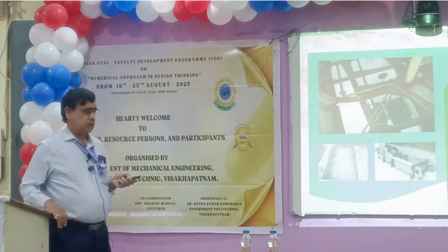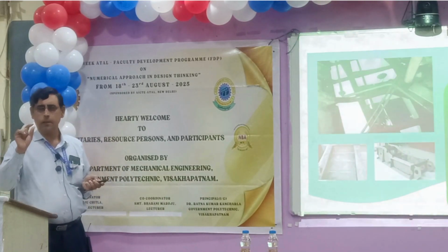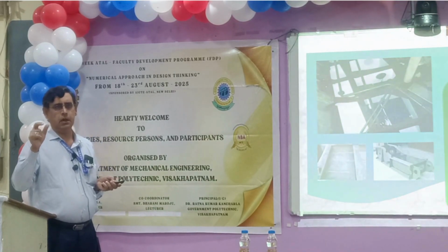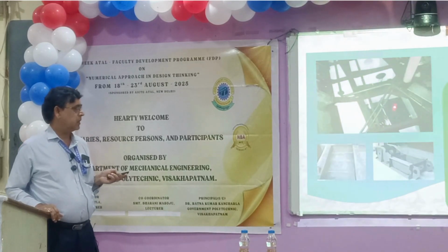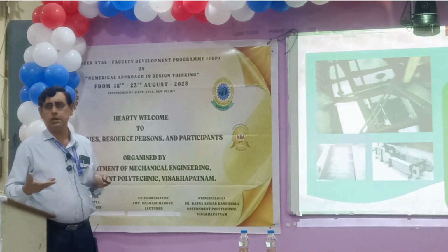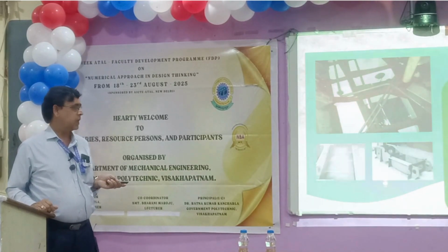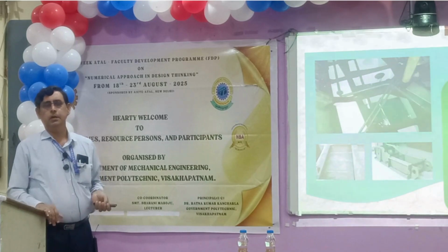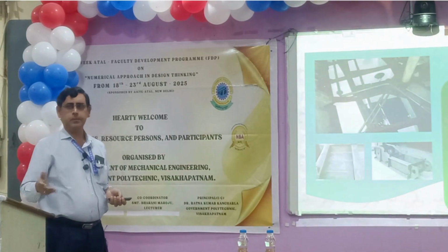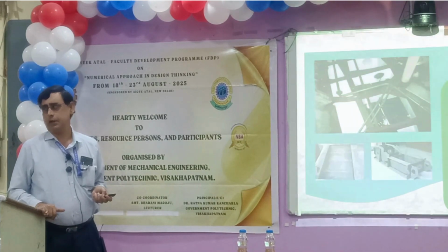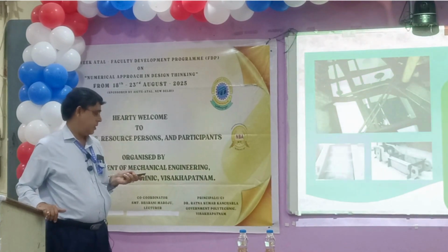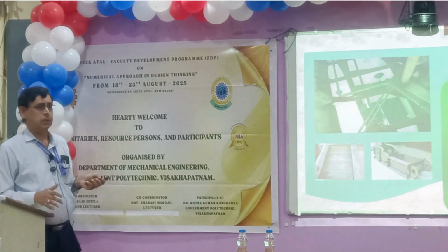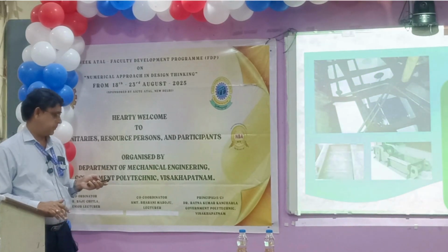And in constrained layer damping, another advantage, rubber works in shear. You know what is shear, right? Shear and tension. In case of this, it actually works in the tension compression mode. Whereas here, shear mode is applied because it's constrained between the two layers. Now, when you are talking of shear mode, the rubber is more effective in shear. So that is why CLD is a very effective treatment, particularly for reducing noise in a particular frequency range.